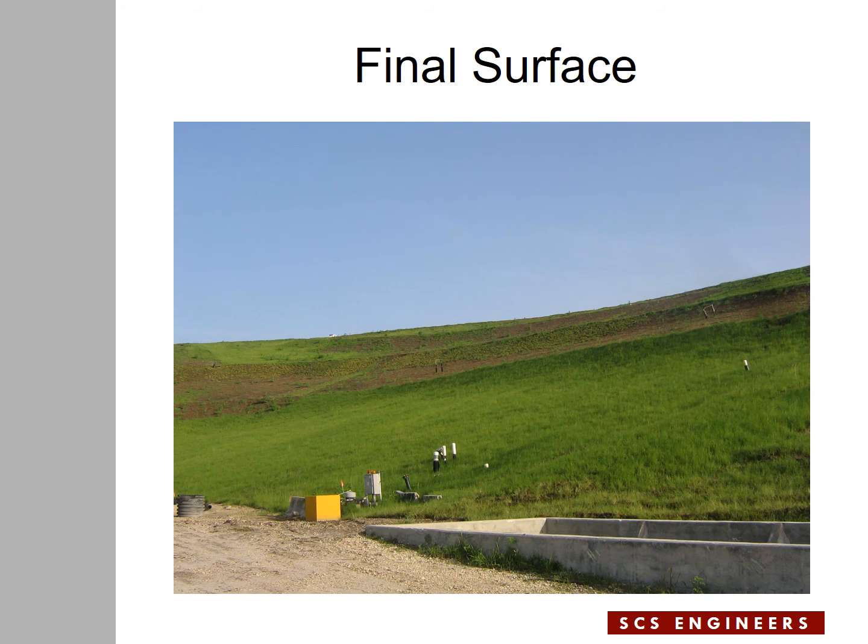So we started thinking what could have caused this, and we arrived at the concave surface phenomenon and its impact on the drainage layer in the composite. Because of the convergence of water in the composite, the hydraulic head in the composite exceeded the thickness of the composite. Water entered the soil layer, and near the bottom there was so much water in the soil layer that it started flowing out of the soil layer, running down the slope on top of the soil layer.